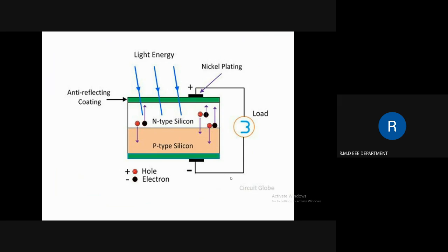Here, the electrons of the semiconductor materials are joined together by covalent bonds. Electromagnetic radiations are made up of small energy particles called photons. When photons are incident on the semiconductor material, the electrons are energized and start emitting. In this manner, electrons are generated. These electrons are known as photoelectrons, and this phenomenon of emission of electrons is known as the photoelectric effect. The working of this photovoltaic cell depends upon this photovoltaic effect.